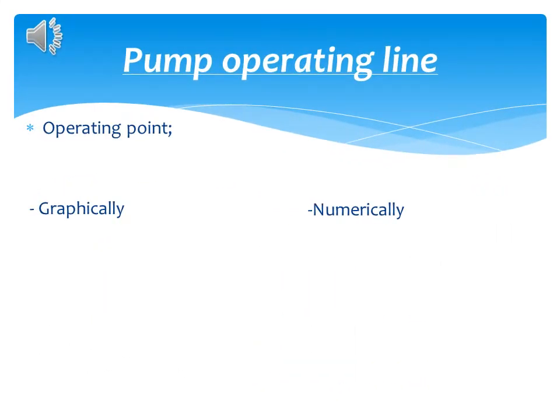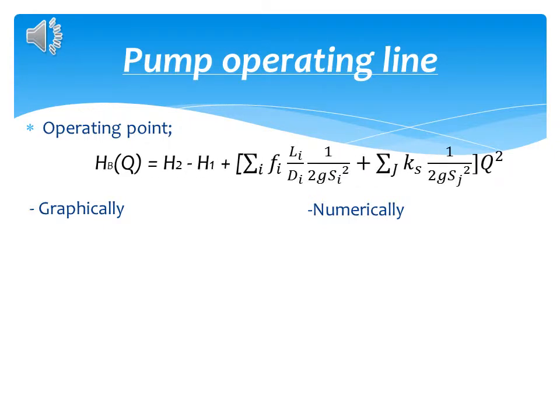Once we have calculated the loading heights and applied the energy balance, we obtain the equation. Our purpose is to determine the operating point, pressure and flow of the pump. For calculation of the operating point, we have to calculate the flow rate which equals both members, and starting from this flow, calculate the height. There are two methods to solve it.